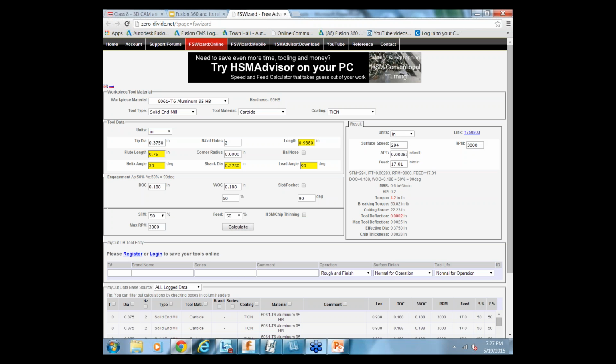Now, that being said, the faster you go, the more material you'll remove, but the faster you go, the more likelihood you'll have bad surface finishes with the Tormach. The machine has a very large, I guess you could call it a perfect storm kind of area, where tool length and bearing play, the bearing surfaces of the machine, will cause vibration.